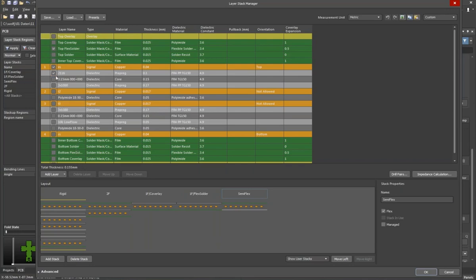Additionally, based on this stack-up, we have the 2F on the inner layers. So here we activated only the layer 2 and layer 3 copper layers plus the coverlay needed for the inner layers. Then we have a 1F built up on the bottom. So we have a polyimide layer on the bottom and the bottom copper layer plus a coverlay covering the copper on the bottom layer.